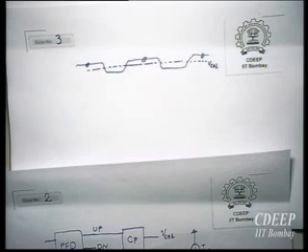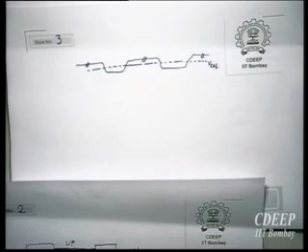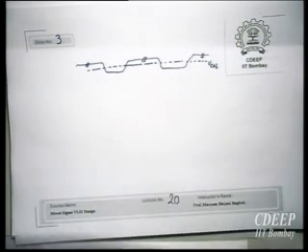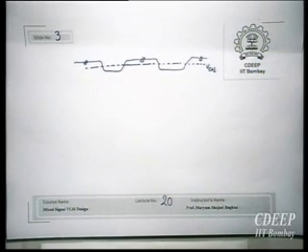This small change will even appear as an offset in the frequency. So there will be an offset in the frequency, and an offset in the phase. But it doesn't lead to instability, no. It will still be stable, because you have a low-pass filter. The low-pass filter avoids instability.